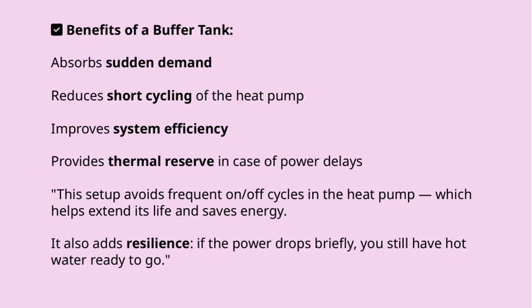Let's talk about the benefits of having a buffer tank in your system. First, it absorbs sudden demand spikes. So, if there's a quick increase in hot water usage, the buffer tank helps handle that smoothly without stressing the heat pump. Next, it reduces short cycling of the heat pump. This means the system doesn't turn on and off rapidly, which is not only better for the equipment's longevity, but also saves energy. It also improves overall system efficiency because the heat pump can operate more steadily without frequent cycling.